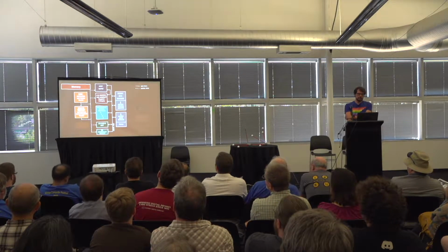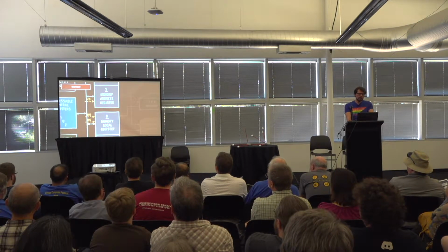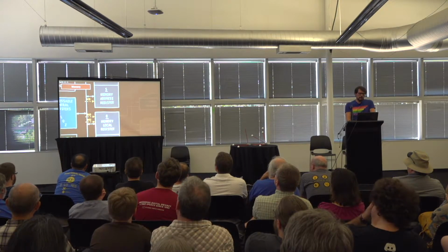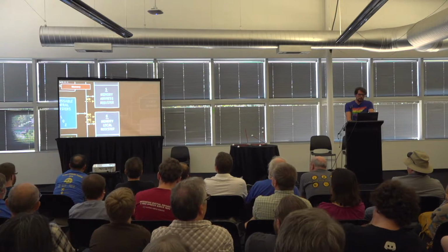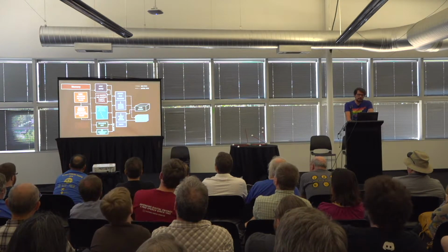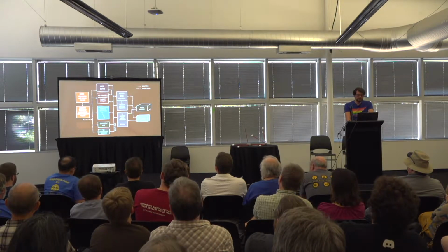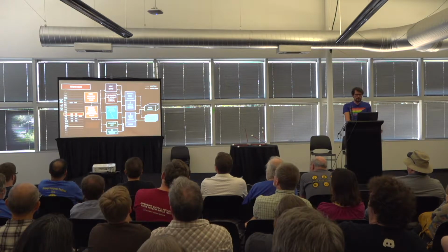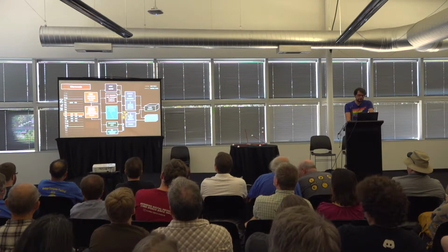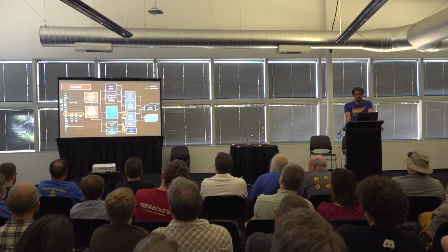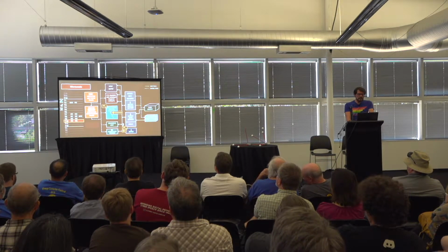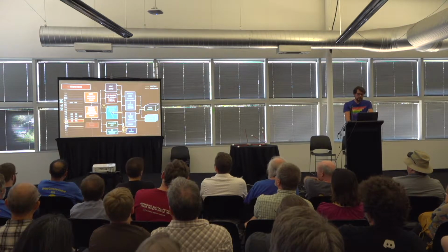Memory is also connected to the write bus. WS will copy the bus contents in the memory into the memory address register, and RG and WG will read and write the G register, which buffers the cell's value after a read and before a write. So in stage 7 of the load instruction, for example, RG puts the memory buffer onto the bus, and WB writes the memory bus contents into the temporary B register. And then at T10, B gets put on the bus and it gets written into the A register.